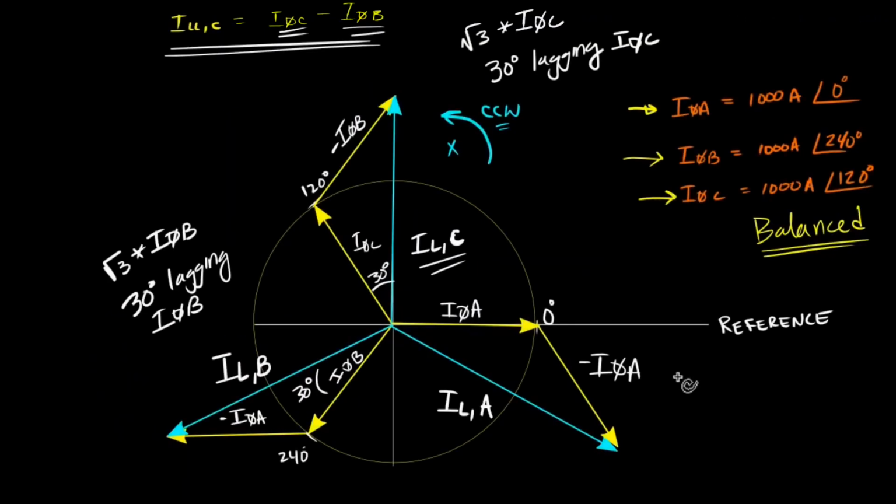Right? Okay, so returning back to our phasor diagram, in this diagram I quickly redrew our line current A like we did in part 5b. So in this complete phasor diagram, we see that phase A current is here, phase B current here, phase C current is here, and in blue we have the line currents: this is line current A, this is line current C, and this is line current B. We see that the line currents have the same magnitude.